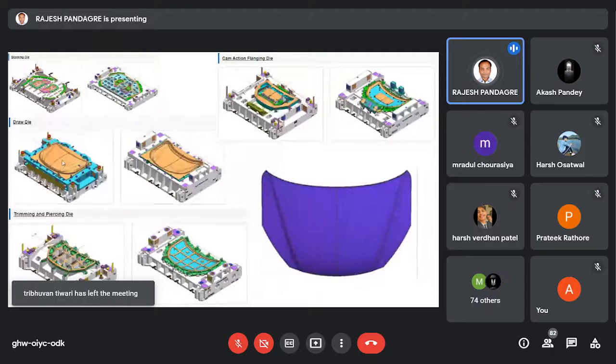After that, to get this shape, basically a grinding operation will be there, and after grinding, a stoning operation will be there, to get this class A as it is, as it is visible on the vehicle. So achieving this class A shape is not an easy thing. Let's say one die is there, the first die. This part shape I'm going to build in 4 stages.